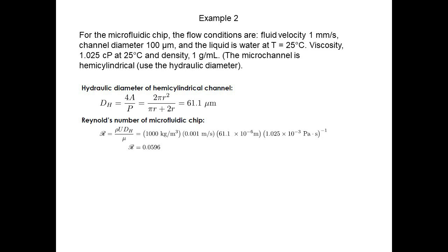The diameter of the pipe is 0.5 meter, the velocity V is 3.6 meters per second, the rho is 1258 kilograms per cubic meter, and the viscosity is 0.96 Pascal second. The final answer you get is 708.